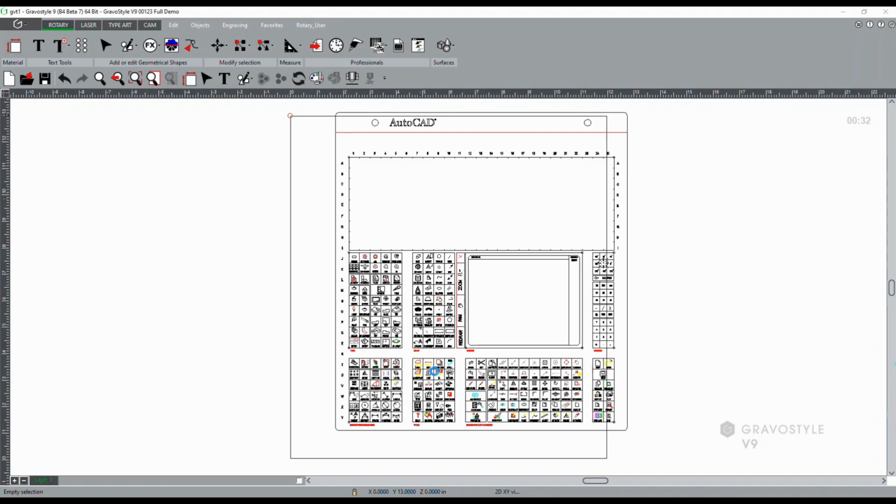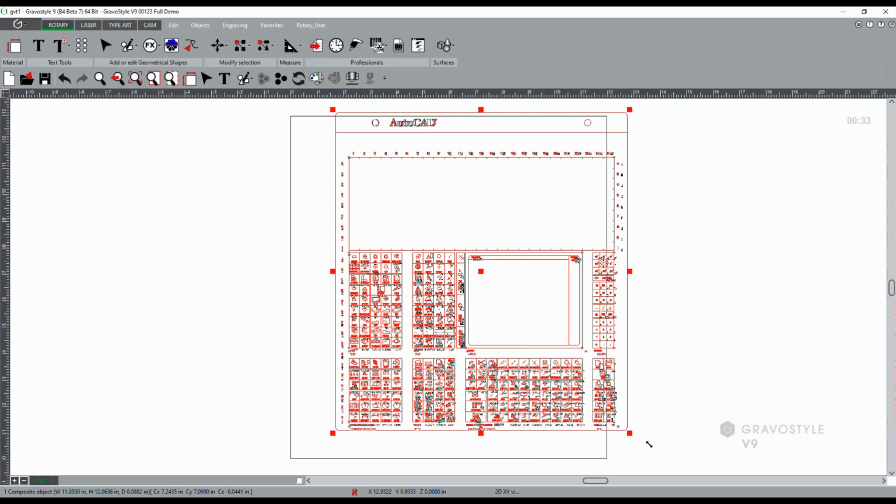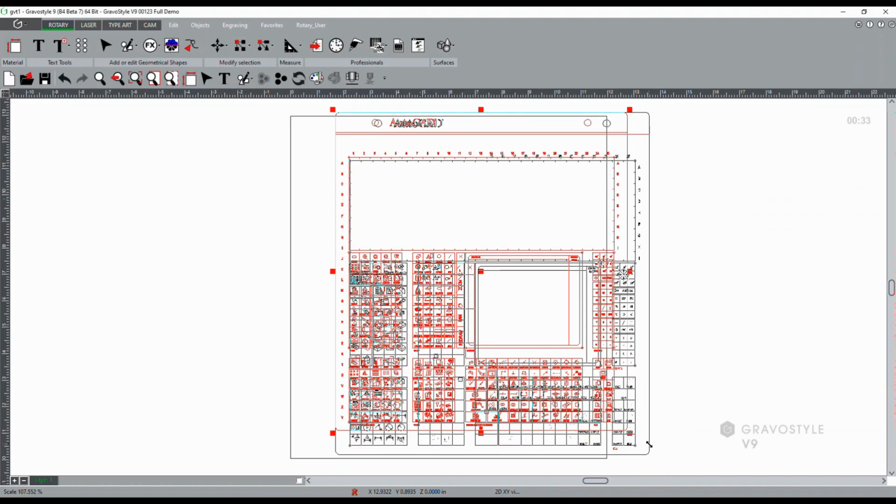Okay. So the drawing will come in. We can see that the entire drawing is selected. The drawing does appear off of my work area, and I can see that I have a little red circle that's following my cursor around the margins. It lets me know that I'm locked to work within the margins. So if I try and select this object outside of the boundary box, it will not allow me to do that. So I'll come down and release my padlock that allows me to work off of my composition page. Now I can go out and select and manipulate graphics freely outside of the workspace.